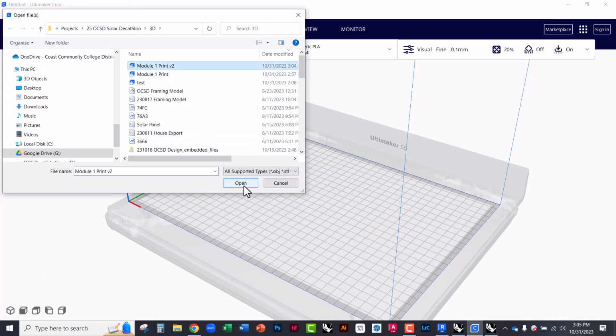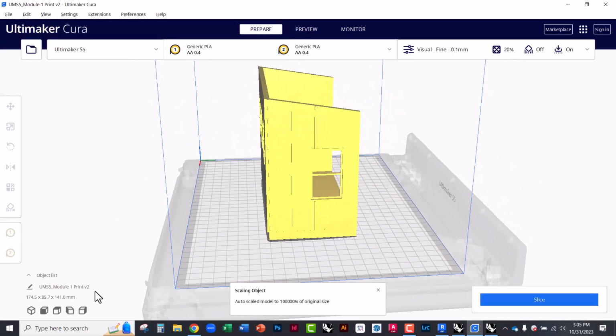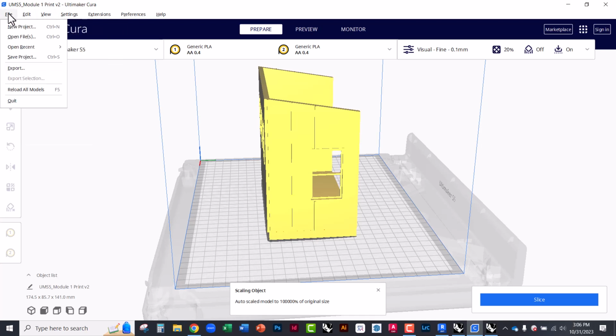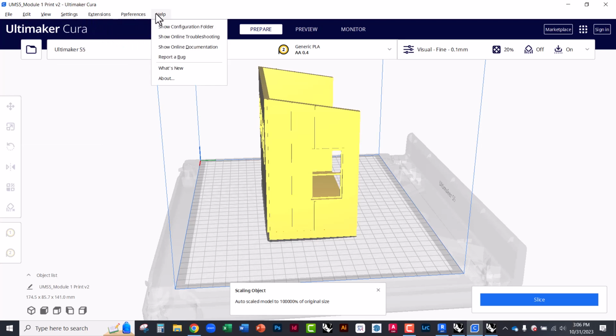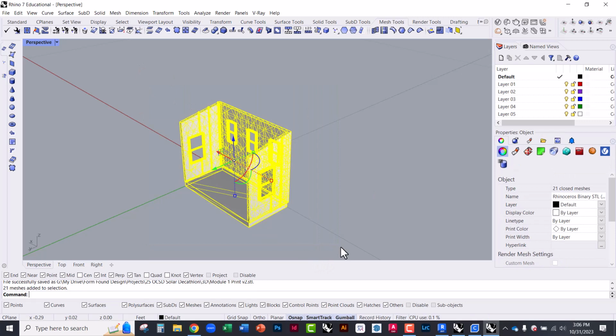This is V2. And you'll notice that it's reading this in millimeters. So one thing that we may want to do is make sure that either we change the units in the 3D print software, which I don't know if we can do easily, or we just export it in millimeters. And I think that's what we're going to have to do here. So it is the right size. Now we just have to export this. And first, let's just change the units. So I'm going to type units.